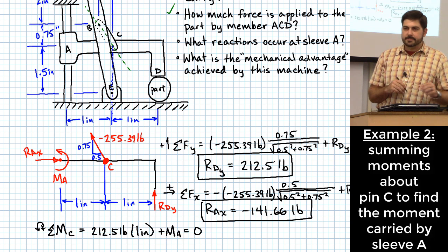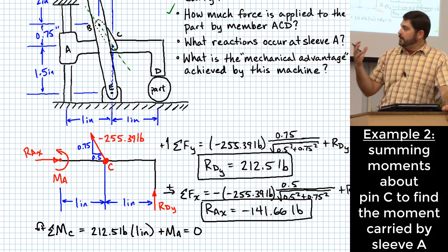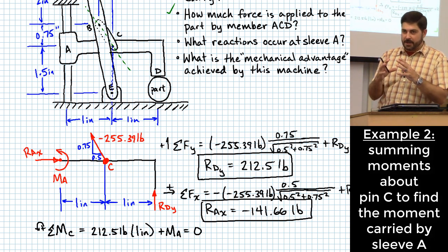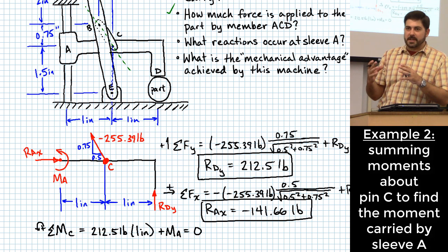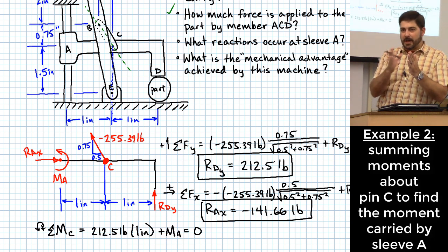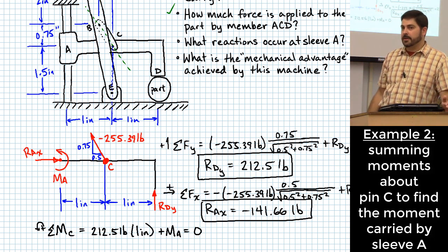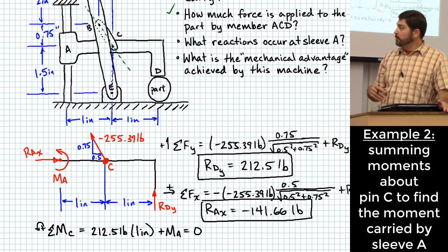So that would only apply if we're talking about the specific body that has the concentrated moment. Is that right? Or would it apply to the whole thing? That feature that I was just talking about, that if you have a concentrated moment and you're summing moments, you just put that concentrated moment in the sum. You can't do that with forces, because with forces, you actually have to think about the length associated with that force relative to the point you're summing moments around. But with concentrated moments, it doesn't really matter where they are. You just include them in the sum. Yep, it's already a moment.